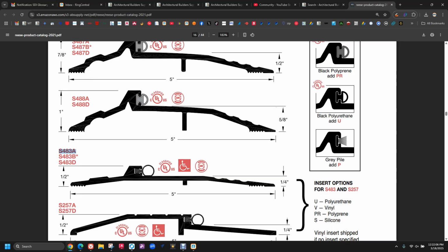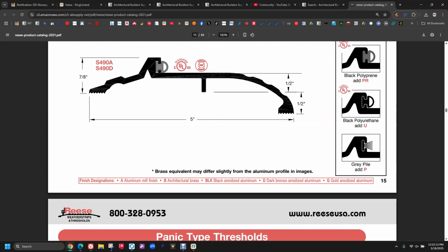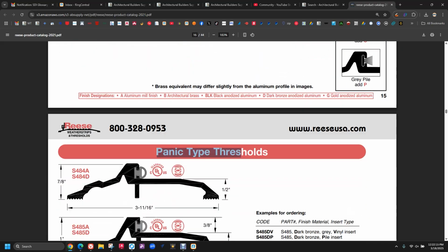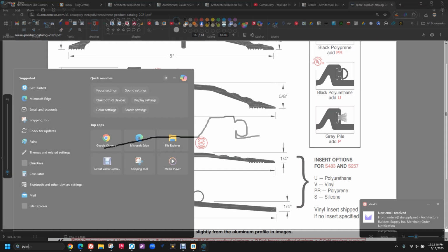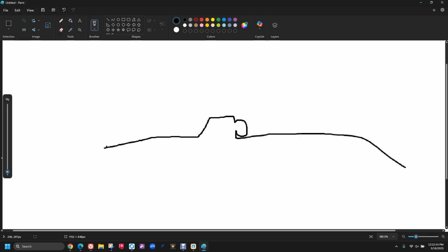Imagine your Pullman latch from a surface vertical rod exit device. It's going to go right back here, and that's why they call it panic type thresholds. Imagine trying to stick a strike for an exit device down on this threshold. You won't be able to, but they go right here. Let's see. Threshold. There's your bottom latch assembly, and here comes your Pullman latch. That's what it's doing.